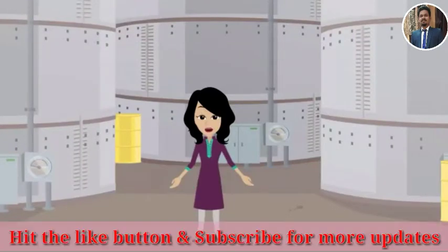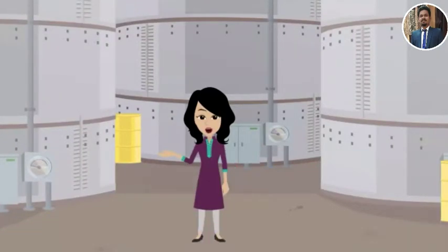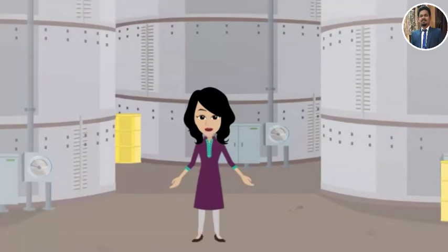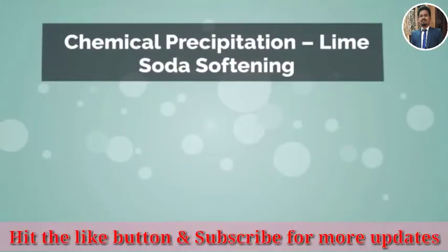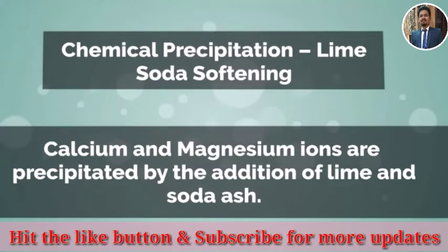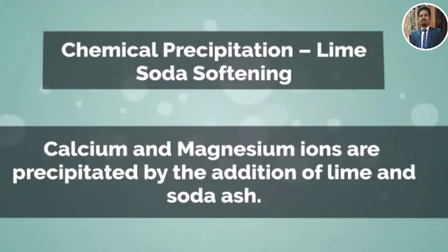The first process in water softening is lime soda softening. Have you ever learned about lime soda softening? If not, let's learn it now. In this process, calcium and magnesium ions are precipitated by the addition of lime and soda ash. Following are the reactions that take place in this process.